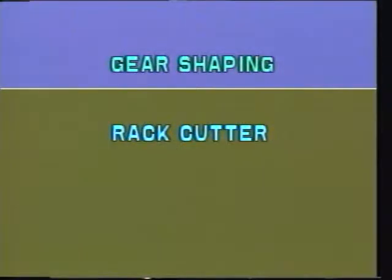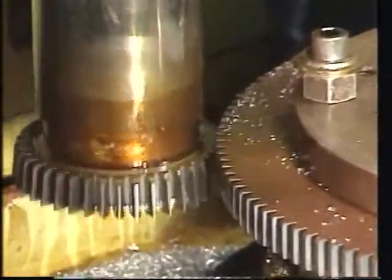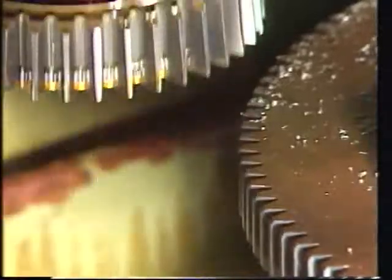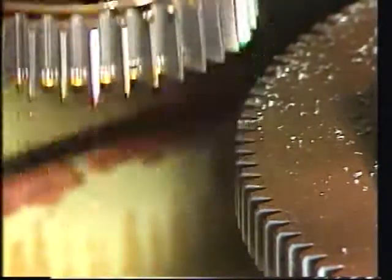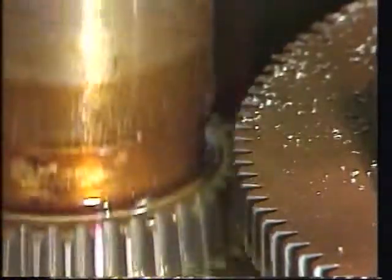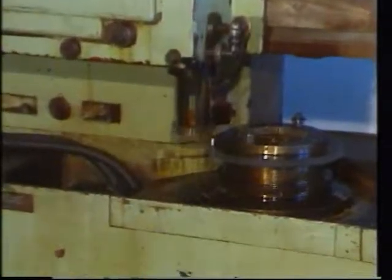Gear shaping can also be carried out by using a pinion cutter. The pinion cutter reciprocates and also revolves in a specific relative motion with the blank. This shaping action generates the involute tooth form, cutting the tooth edges facet by facet.